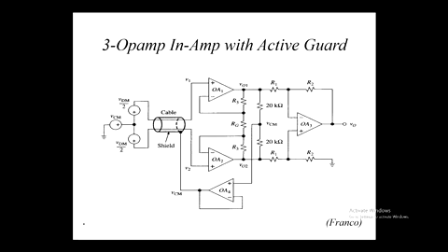Remember, I might have mentioned to you a good way to analyse this circuit is to do it separately for common mode and differential mode. Like if V1 and V2 are equal, we'll say V1 equals V2 equals VC. This voltage here is equal to V2, so that'll be VC. So this will be VC here. This voltage is VC, so that one will be VC because we've got negative feedback. So that point will be VC as well.